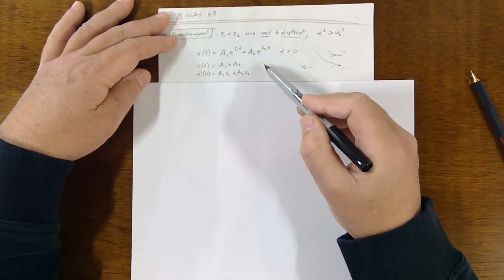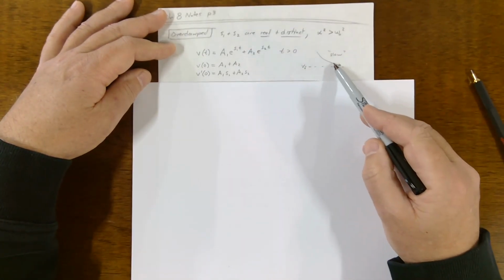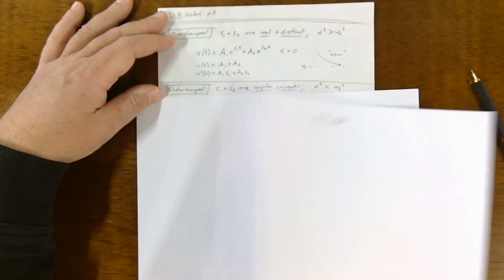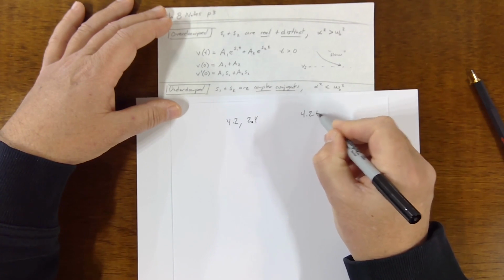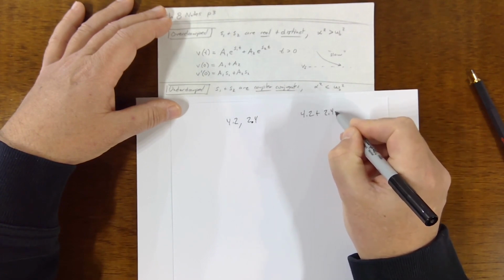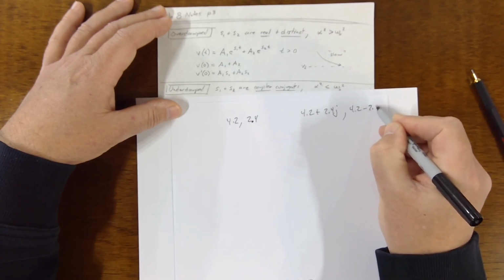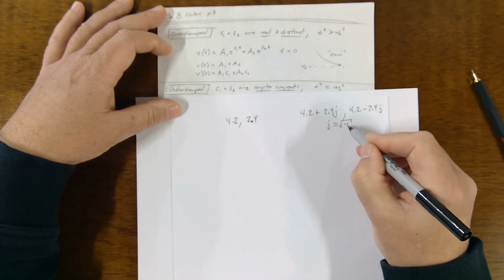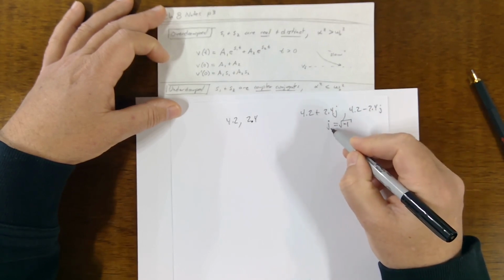And that can be used to solve the system of equations. So this is for underdamped, when this thing is decaying very slowly. All right? If S1 and S2 are complex conjugates, and what's a complex conjugate? A complex conjugate is something like 4.2 plus 2.4J and 4.2 minus 2.4J, where J is the square root of minus 1. J is just like I in regular mathematics, but for us, I is current. So we have to use J.